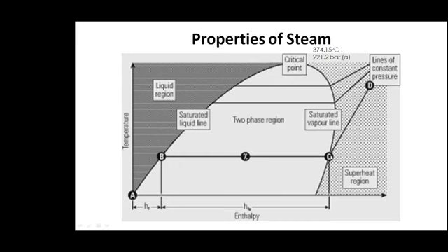So here the point C is 100% saturated steam. If you further heat it, it becomes superheated. Superheated steam is generally not used in the process. It is used only in power plants. In industrial applications, you will hardly find superheated steam being used. It should not be used because there will be a delayed heat transfer. Superheated steam behaves like a perfect gas. So the heat transfer coefficient is poor, the heat will be transferred very slowly and it will delay the process. So we don't use superheated steam in process heating applications.